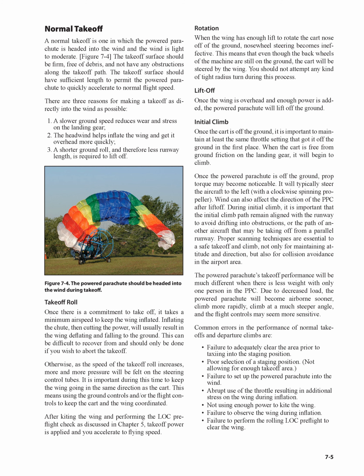Takeoff roll. Once there is a commitment to take off, it takes a minimum airspeed to keep the wing inflated. Inflating the chute, then cutting the power, will usually result in the wing deflating and falling to the ground. This can be difficult to recover from and should only be done if you wish to abort the takeoff.